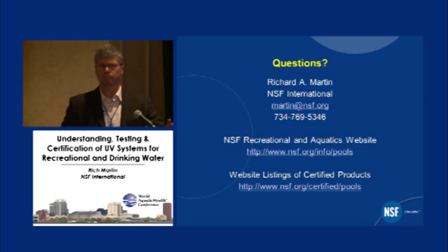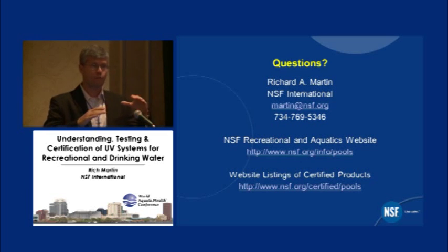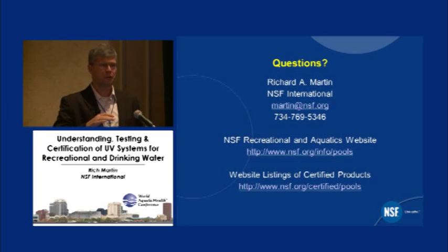I don't know if I made that clear, but turbidity is relevant, but we actually use the UVT to monitor and test for it because it's more all-inclusive. You can have very non-turbid water but terrible light transmissivity due to oils and other materials that are light diffracting as well. They just don't look cloudy, but the light can't get through it.